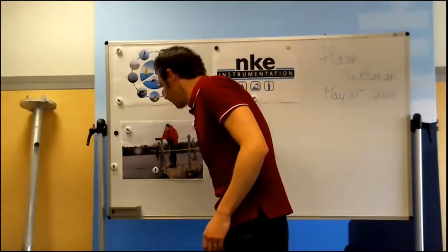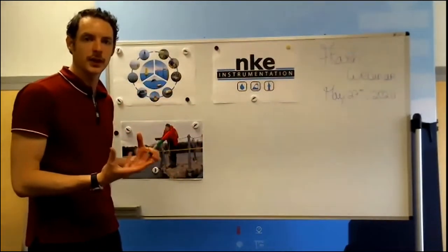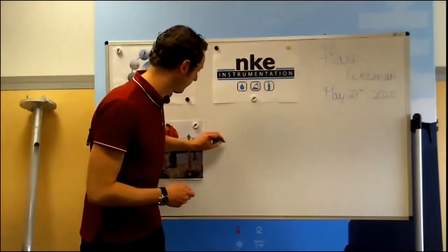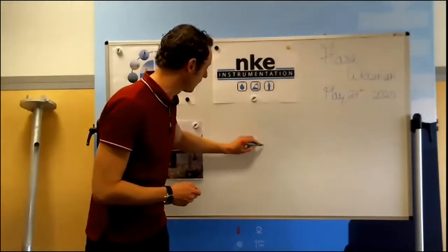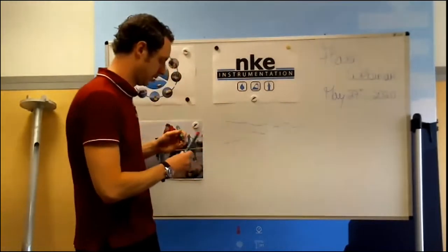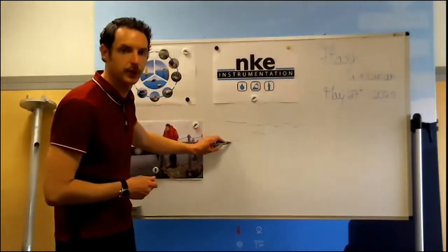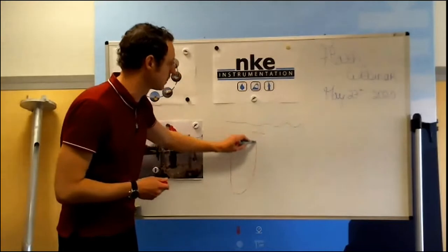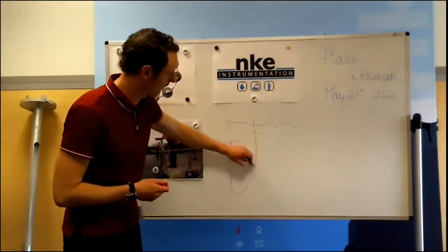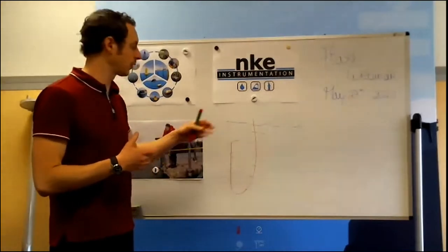Typically, a pressure condition can be ideal if you are on the field and you don't want to manipulate any element. You just have your sonde on a rope, and what you do is you will determine two depths. This is my water. And you will say, I want the sonde to start to measure when I reach this depth, and I want the sonde to stop measuring when I reach this higher depth. So the sonde is in the water, reaching the depth, making the profile, coming up, storing the data, and waiting again for the next condition to start and stop.